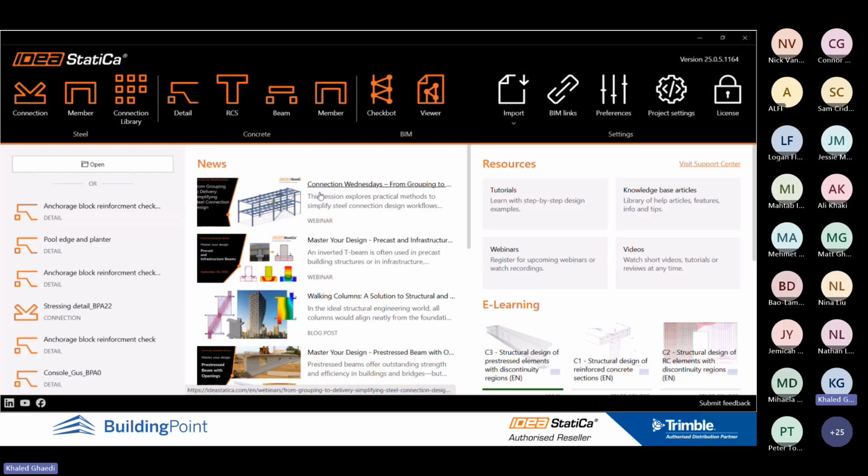After putting the reinforcement, you can simply go to the tools tab. Here we have the cutting edge technology, which is the topology optimization. You will get the compression and tension zones with red color and blue color. For example, here you have the compression zone, the red zone. And if you recall, we put the load exactly at the top of the bearing plate. So that's why, very specifically, you can see how the compression and tension zones are shown by the software. Based on these zones, you can update the reinforcement to have a better design.